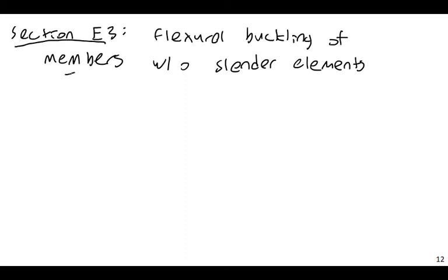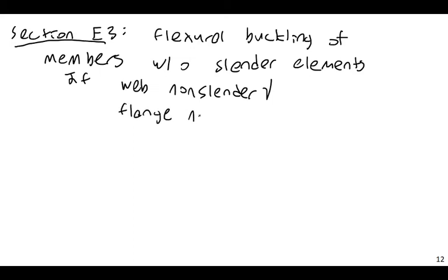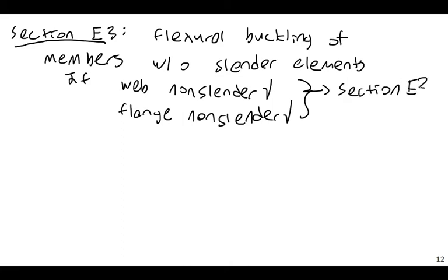So in other words, and again, this says without any slender elements, you have to run the check and see: okay, if the web is non-slender, check, and the flange is non-slender, then you're good, and you can use section E3. If not, then you're going to have to move to some slightly more challenging sections.